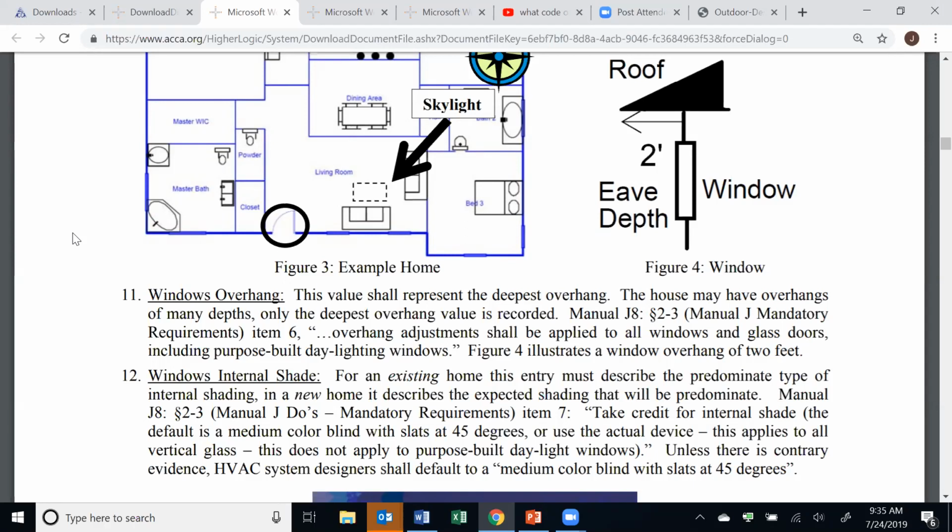Okay, I'd be curious. I know when I was building official in Granbury, a lot of the houses built on the lake, for example, that back wall would be 60% glass, but it would be on a 12-foot overhang back porch. So most of the glass is on a 12-foot overhang, but what happens when that's facing south and I've got a 16-inch overhang on the east? Does that window overhang include porches? Would you want to have 12-foot listed as your window overhang in that scenario? Or is that basically just the rest of the soffit corners?